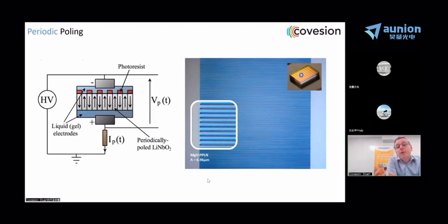So in this example, we have a grating that is about 6 microns in period. And you can see from that zoomed in picture that we've got very high quality domain formation. We have very uniform domains. We have no missing periods. We have a well-controlled period, and crucially, we have a well-controlled duty cycle. So the duty cycle is very close to being 50-50, and that's important to ensure high conversion efficiency.